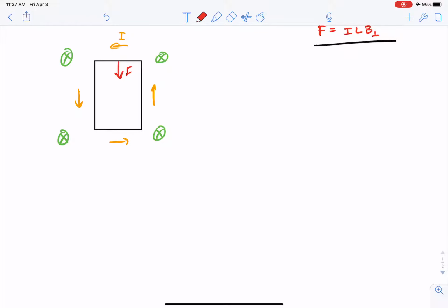Okay, now let's do the same thing on this wire here. Again, with this up vertically on the vertical surface, your arm will be going down towards the ground in the current, yeah? So then you rotate your hand again until your palm is facing away from you. This is kind of an uncomfortable one to do. So then your thumb is pointing to the left. Okay, I'll leave you to practice on the other two sides. Make sure that you get these right. Okay, so they all end up pointing inward.